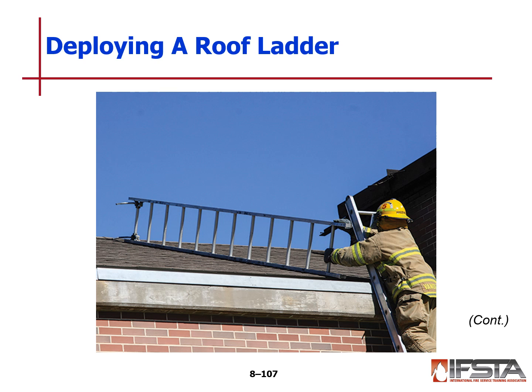Next is deploying our roof ladder. You want to go ahead and have your hooks out and deployed, locked in. As you climb the ladder, you find the balance point of your roof ladder. You find that balance point, you get it up on your shoulder, climb it, and then you're going to shove that roof ladder, like it's pictured here, along its beam until you get close to the peak, and you're going to rock it on over and lock those hooks into the peak of the roof right there.